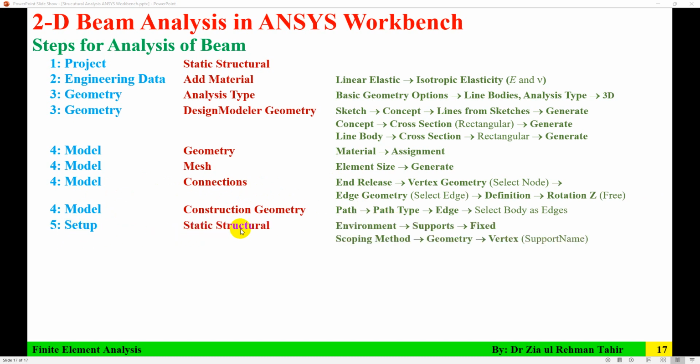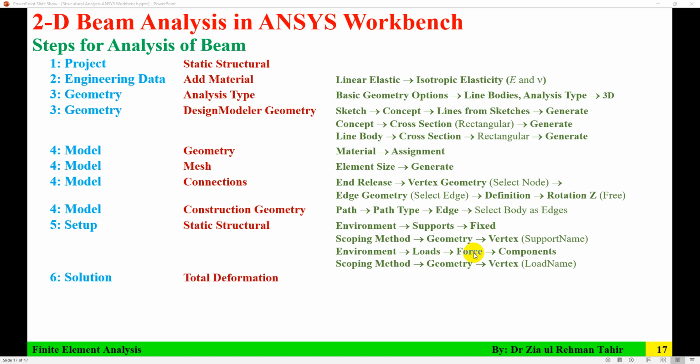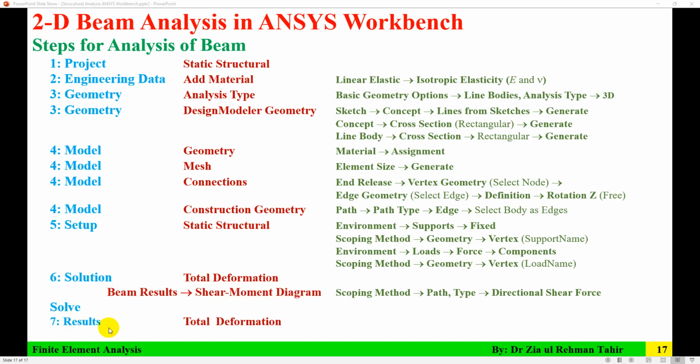This construction geometry will help to draw the shear force diagram, bending moment diagram, and deflection curve. And in the setup, in static structural, we need to apply boundary conditions. Both ends are fixed boundary conditions, and then a concentrated force is required. Then in the solution, total deformation is required to get maximum deflection, and then beam results, the shear moment diagram, are required, then solve to get results, and then interpret those results.